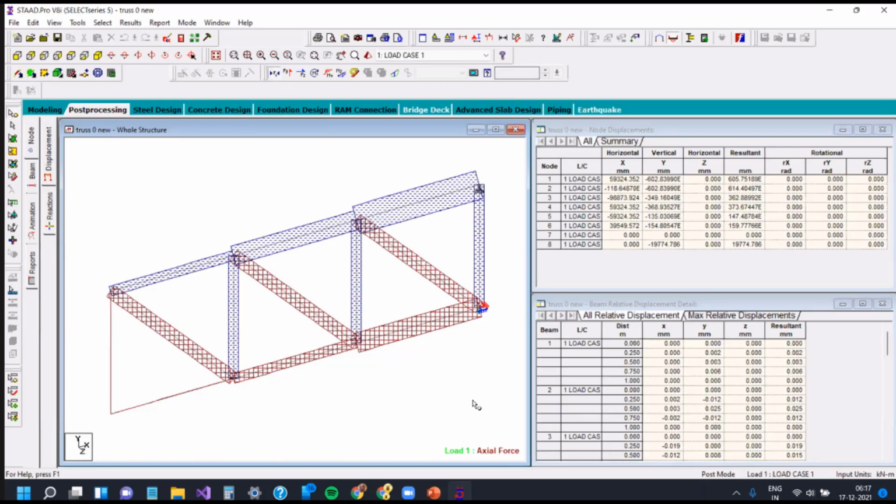That's really fascinating to know how the trusses offer load resistance. So this is a very beautiful example to say that the vertical members and the inclined members are constant because my shear force is constant throughout. Now the chord forces vary because the bending moment is 0 at the edge and maximum at the fixed end. Okay, good and a nice example.